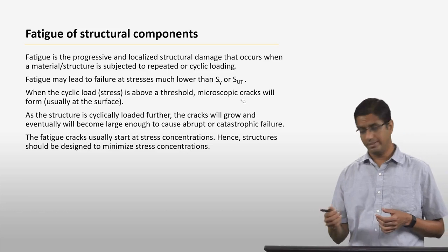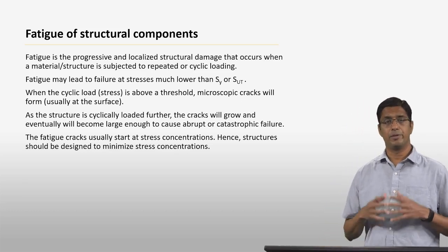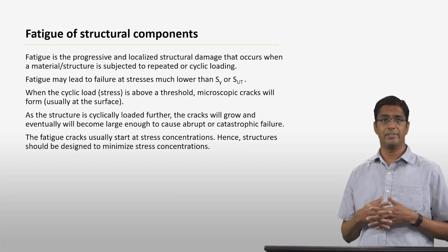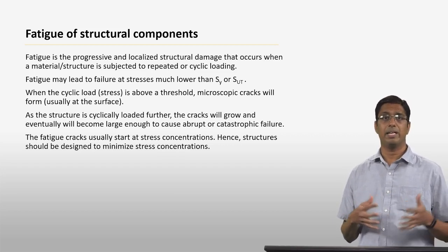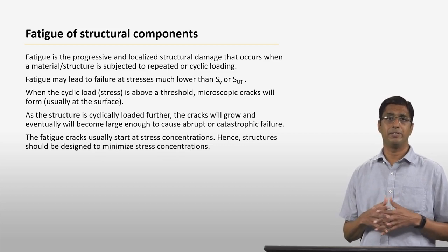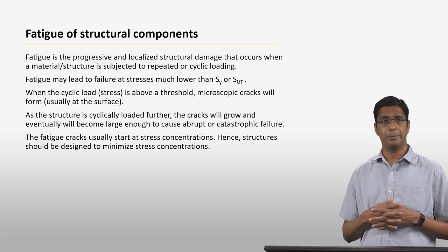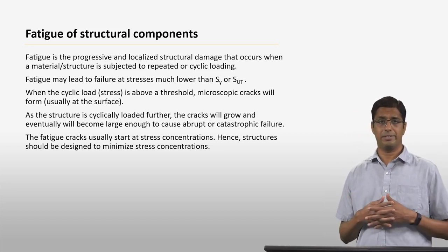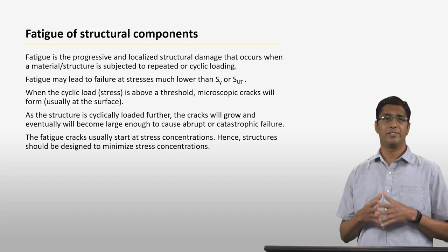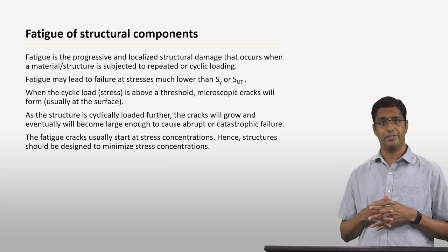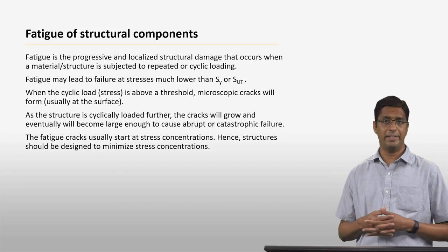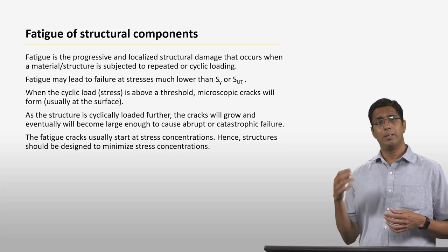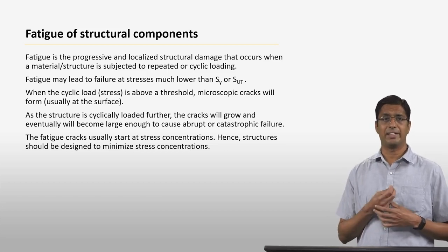And you might think, why is this important? It is important because if you look at engineering structures, almost 90% of the failures that you see in service are due to fatigue. So fatigue is a very, very important part of failure analysis that you have to take into account. And the reason that we have to worry about stress concentrations is because often these fatigue cracks start at stress concentrations. So essentially when you try to design a material or design a structure, you try to reduce the stress concentrations as much as possible because these are the points where this fatigue crack starts.